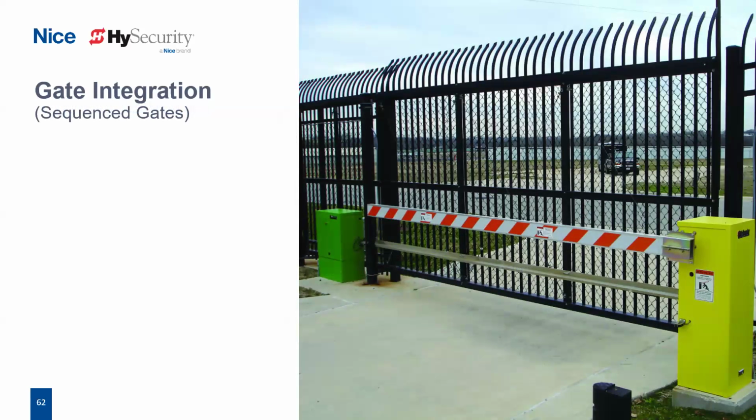Sequence gates are typically going to be a slide gate and a barrier arm. Once given an open command, the slide gate starts to open. When the full open position is reached, the barrier arm will also then be in the full open position. Also, during times of high traffic, we could leave the slide gate open and cycle traffic with the barrier arms, as they can get a full 90-degree open within 2.5 seconds. However, this does require special loop wiring, which we're happy to help you with as well.